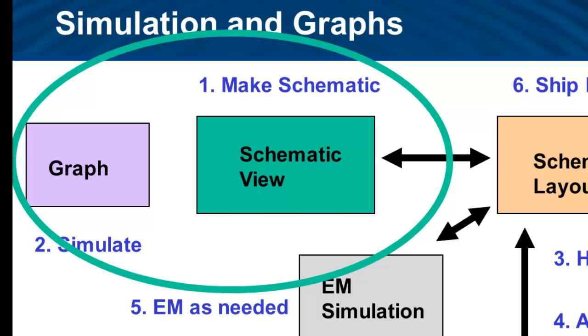And then we're going to make graphs. And we put measurements on the graphs. The measurements, as we'll see, will actually control all of the simulation. I would like to point out this actually is very different than other software you might be used to, where a lot of the control is driven in the schematic. We, on the other hand, like to control everything in the measurements, believing it actually has some useful benefits.